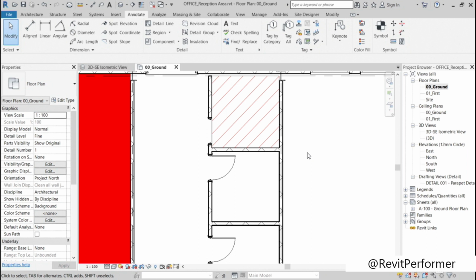And what you'll see is then the difference between the two. And again, more importantly, if you've got hatches in AutoCAD that perhaps adhere to these different settings, you can obviously duplicate existing fill patterns in Revit to match the hatches that you might be using in AutoCAD drawings, linked or imported CAD files, etc. So let's go back to our Manage tab.